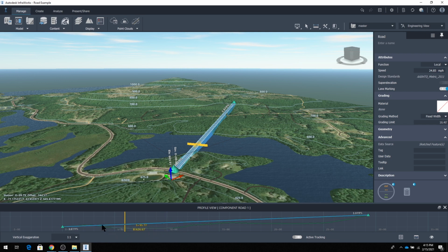The blue line is the new road that we just built. It's the profile of the new road. Here's station 0. And if you're driving right, going uphill this way at 4% almost. The green line down here is the existing ground. So we have to put a lot of fill over it to get to this new line. How much fill? Let's figure that out.